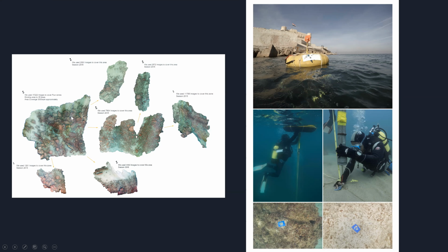For example, in 2014, we built around 20 points or more, distributed all around the site. After I make the 3D model, we put in the georeference data and it's automatically georeferenced. In 2015, 2016, 2017, and so on, we did the same procedure. Before we take the photographs, we put the ground control points and do the georeference. Since the whole site is in the same coordinate system, the orthorectified images and the 3D models are automatically merged together.